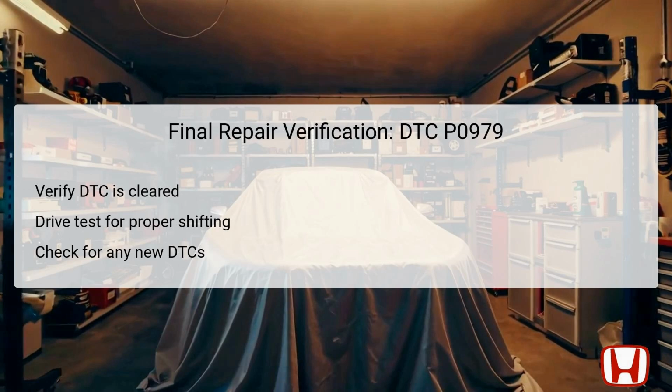After completing all necessary repairs for DTC P0979, it's essential to conduct a thorough final repair verification process to ensure all issues have been addressed. First, use the HDS to verify that the DTC has been successfully cleared from the vehicle system. Following this, a drive test should be executed to ensure that the transmission is shifting properly and consistently without any